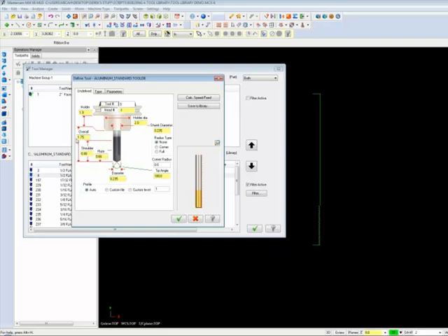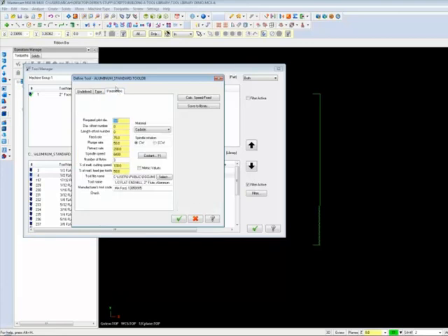To use the geometry we created to define the tool shape, click the Custom Level radio button, enter Level 2, and press Enter to see a preview in the preview window. Click the Zoom button to see a close-up of the tool tip. Click on the Parameters tab.